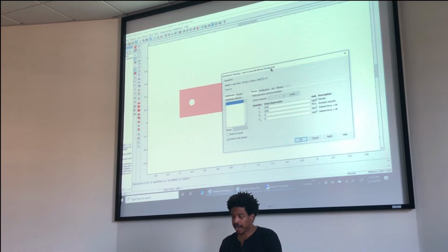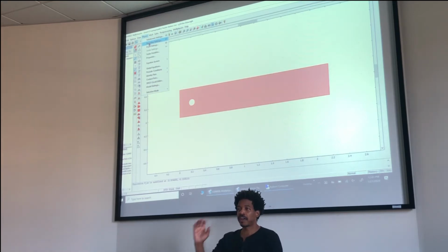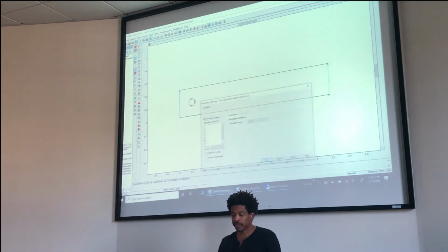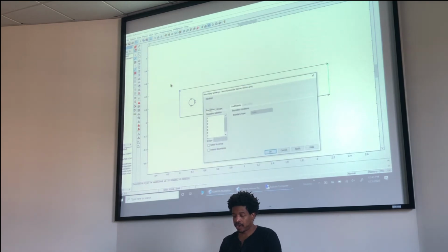Okay, now let's get out of here, and then let's go to the boundary. Because remember, I told you there's subdomain and there's boundary. With everything you model, you define the subdomain and the boundary. So in this case, here's a boundary. And that's just the edges. Okay? So on this edge, let's highlight it. It says this boundary is the inlet. Okay? So something's coming in. And this boundary condition is velocity. I could change it. It could be pressure. But it's velocity. So something's coming in.